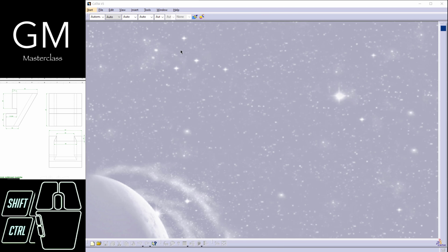And right here I have 3 views. This is an advice: when you want to create a 3D model, you should start with the view that contains the most information possible. As you can see, this is the one that contains the most information possible, so I'm going to start creating this view, right? The second thing is the dimensions, right?